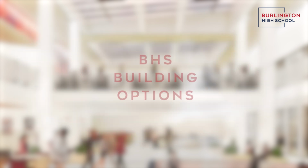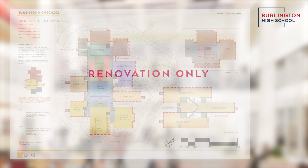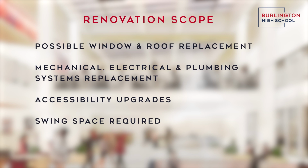When considering what's best for the high school, there are categories of options. The first category is to upgrade and renovate the existing building. This approach is code compliance upgrades only, including energy, accessibility, and life safety. Scope may include roof or window replacement, but would definitely include mechanical, electrical, plumbing, and fire protection systems replacement, and accessibility upgrades. It is assumed that this option would require temporary modular swing space during construction.